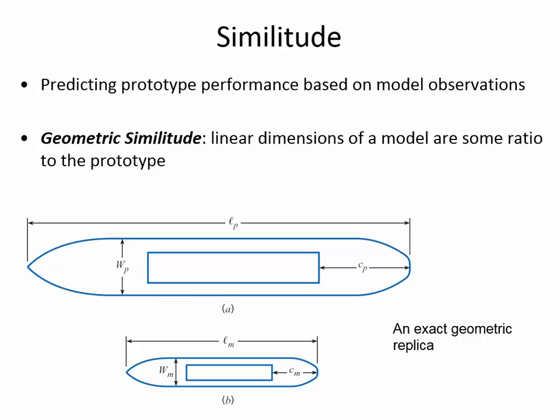One of the main principles that's employed in constructing a physical model is the idea of similitude. And geometric similitude is what people are generally familiar with in the relationship between models and prototypes. Geometric similitude is just the idea that you should have a scaling of the dimensions, so that if you have, for instance, a 1 foot long boat as a model and it's 100 to 1 scale, then the prototype you're trying to model would be 100 feet in length. So every parameter from the model to the prototype follows the same geometric ratio.